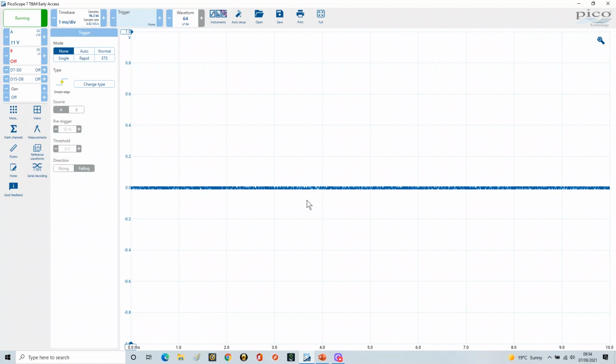Which you'll see a signal every now and again as I'm talking. This is really important that you actually see this. So I've got a signal which is a 1 kilohertz signal, 1 volt peak to peak, but I've put the signal generator into burst mode, so it only does one cycle once every half second.